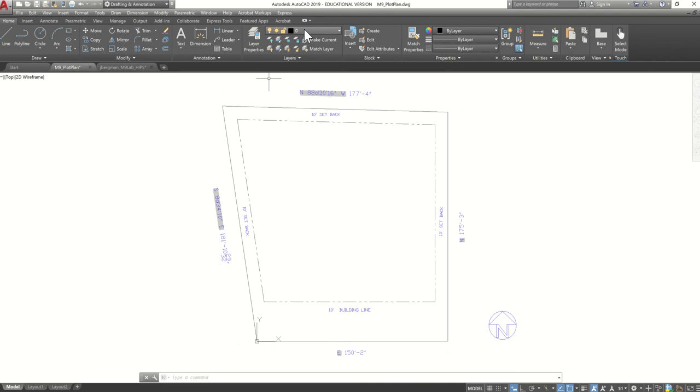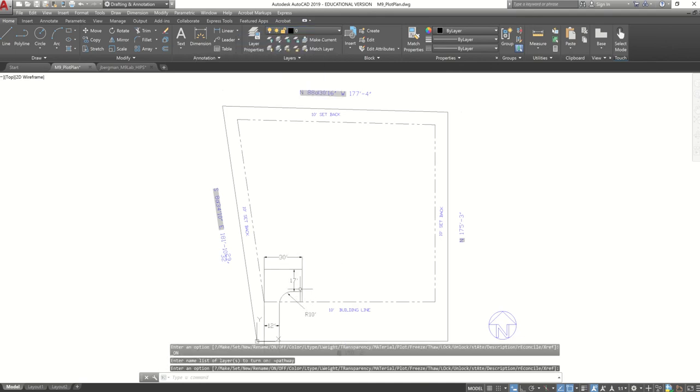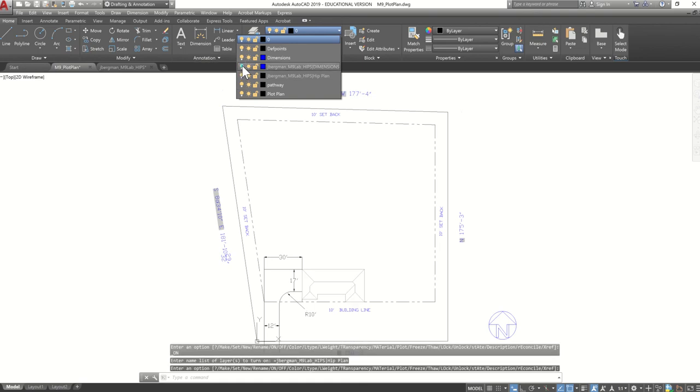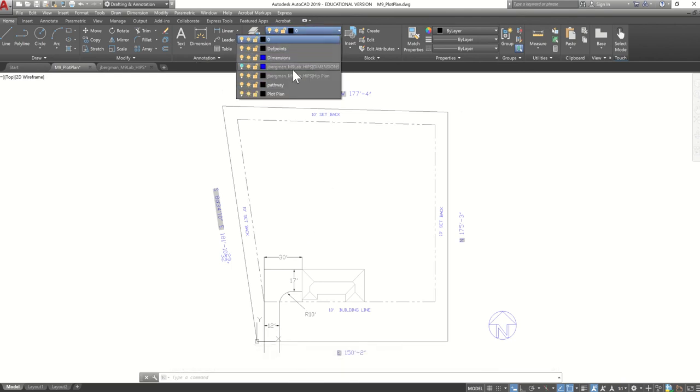And then part 3, we are actually going to first draw a pathway so we know actually where to insert our hips drawing. And then we'll use external references to actually insert the plot plan. And I'm going to hide the dimensions layer. Also, it's important to note that you can see that it says jbergman_m9 lab, blah, blah, blah, dimensions. Because it has the drawing name in here, we use the insert method of external references instead of the bind